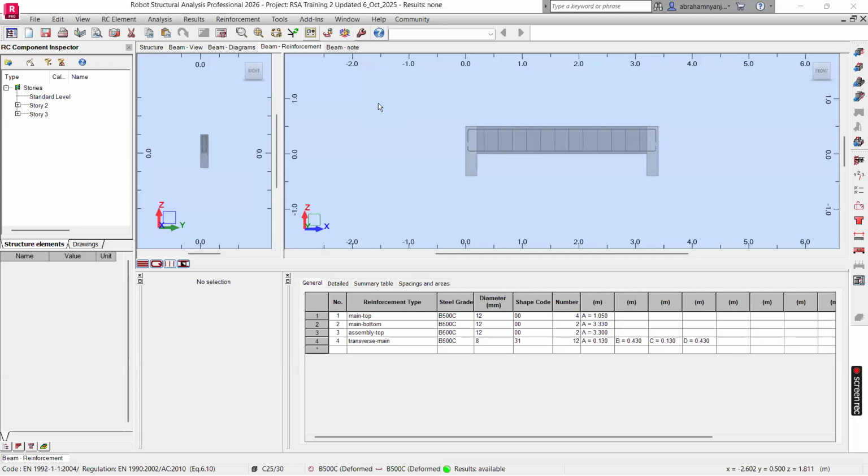And the assumption is if your structure can stand the worst case scenario, then what will happen when your water tank is empty, meaning the load will be very small. If you had maybe 20 kilonewtons per meter squared when it was full, and when it is empty it has 1.5 kilonewtons per meter squared, your structure will be carrying something very small.